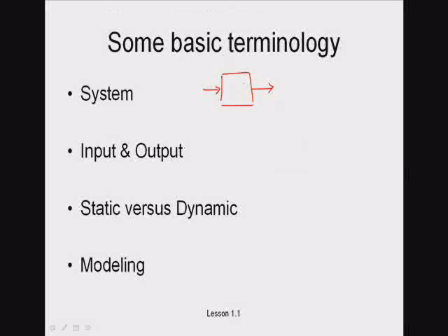So if we just have one entity, maybe this is, from 325, a mixer. So we've got two different streams coming in, and then we have a mixed stream coming out. So for this case here, we would define our system as being around this unit, and so it's clear the arrows coming through the dotted line are your inputs, and then the arrows coming out are the outputs.